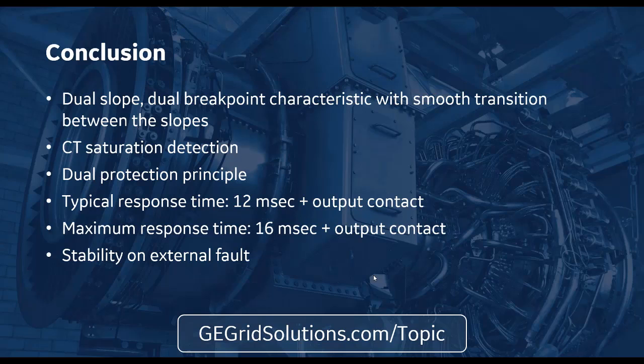I think the paralleling comes in mostly as a retrofit consideration. Can I really run that CT connection? I might have two pieces of switchgear right next to each other, and I might need to run cabling to a control room somewhere. Do I really want to run two sets of CT cabling, or can I get away with running one? So, as I said, I don't really recommend paralleling CTs unless you look at it very carefully.